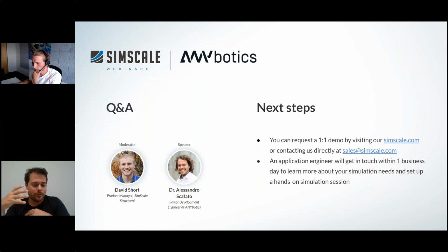And then you do this for various situations, right? You can say, for example, we expect the robot to walk for that percentage of its lifetime on a surface, and from another percentage of its lifetime, it's going to do stairs, and from another percentage, it's going to do this, and you add up everything into a Miner's law, right? And run your fatigue test that way.